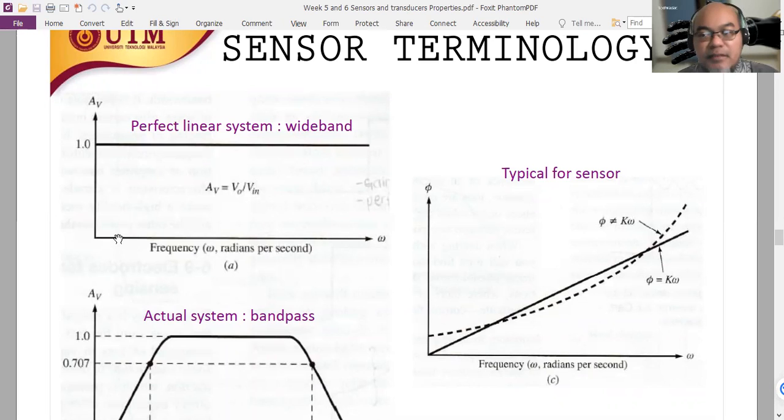For example, body temperature varies very slowly. Maybe you have variation between day and night, but only slight variation, because our body has a body temperature regulation system. But the heart signal may contain a little bit faster frequency, with bandwidth between 0 and about 100 hertz. Muscular activity also has a bandwidth of about 0 to 100 or 150 hertz. Neuronal activity, the brain activity, has much higher frequency, in the range of 1000 hertz, for example.